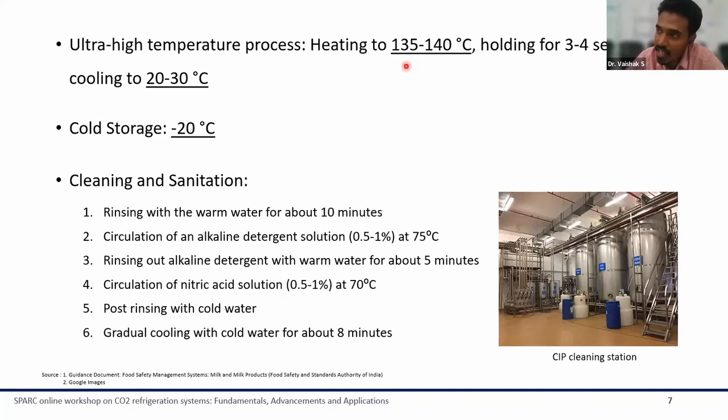Sometimes there is also a requirement of very low temperature cold storages. A typical example is the butter which is produced. If we want to improve the storage or shelf life of that butter, it has to be stored at a temperature of minus 18 degrees centigrade. So there will be a cold storage requirement of minus 18 degrees centigrade in dairy applications. And in addition to butter, if ice cream production is also there, it requires a temperature of minus 18 to minus 20 degrees centigrade.